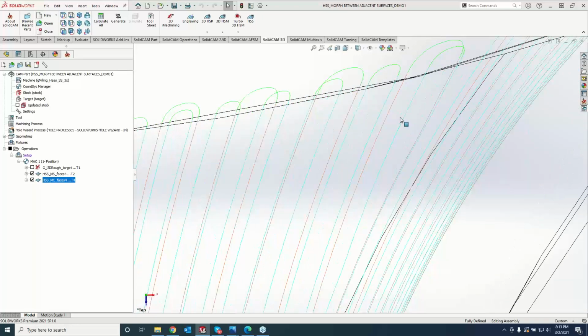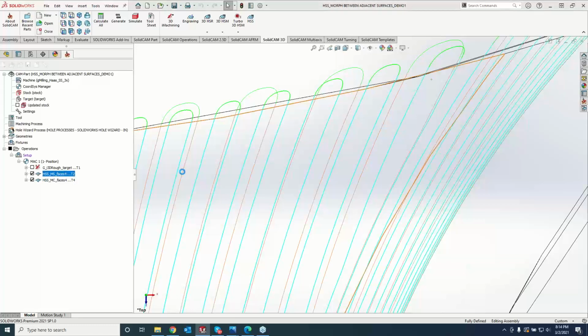Now you may ask, why is it doing that? And I'll have to do some research on that because I don't know, unless Greg, you know right offhand, why our gaps would be a little bit larger based off of boundary curve versus surface. Yeah, I'm not familiar with it offhand. Do you have gouge checks on both operations? Yep. Can you turn the gouge checking off on each? Absolutely.